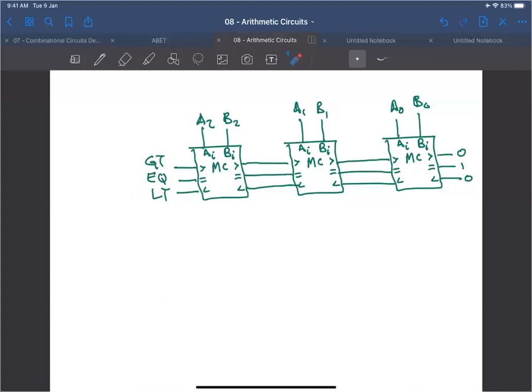So these are the inputs of the comparator, plus these are the outputs. These are fixed inputs. They never change. So you can consider them as, I mean, if you want to design it, no, actually, you can't. If you want to design it using a K-map, then you have a 5-variable K-map. You cannot just assume that the other conditions are not there. But if you want to use a K-map, then there are some don't care conditions, right?